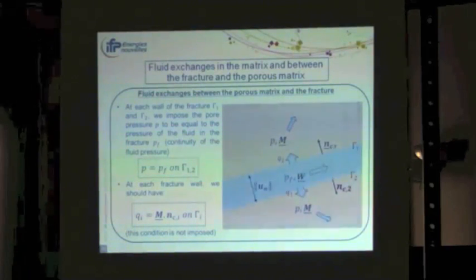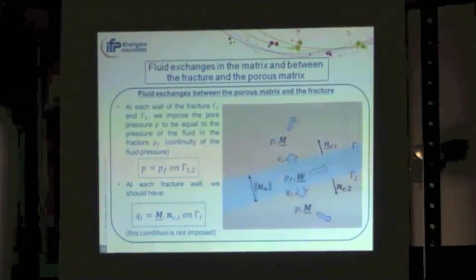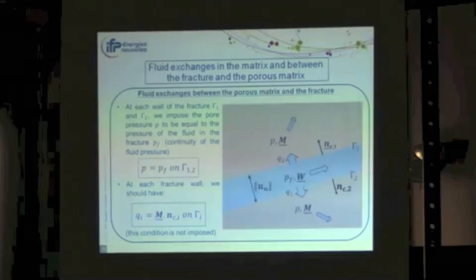You have discontinuous pressure. Yes. And you impose the continuity with some Lagrange multiplier. Yes. Other models, for instance, have discontinuous fluxes and continuous pressure. And why do you find this way is more convenient? I think in this way we don't have to introduce different shape functions, so we just have to multiply by the Heaviside function, the classical shape function.